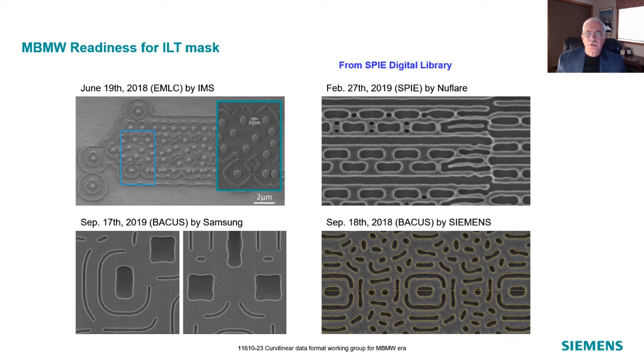Multi-beam mask writers came to the rescue. Grayscale raster writing makes write time independent of pattern complexity, while massive parallelism increases area coverage rate, resulting in reasonable write time independent of mask pattern complexity. Finally, curvilinear OPC output can be made manufacturable.